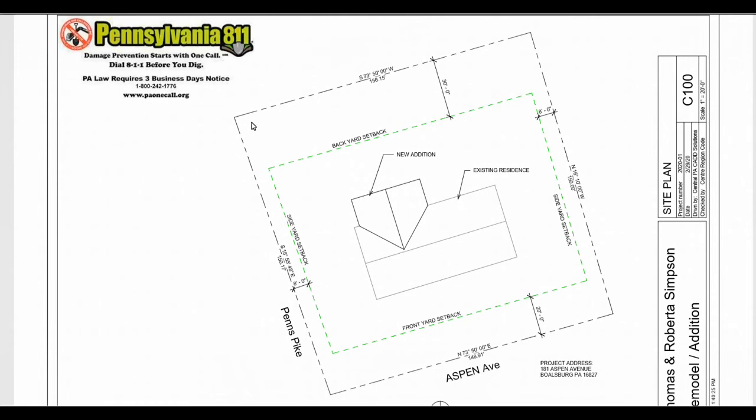And a lot of times in the corners, there would be iron pins that identify or locate the corners, and that would be your starting point. So a lot of times you may see those on the drawing. Like I said, a lot of older site plans, you're not going to see iron pins. If you would go out and actually look for those, you would find strange things for iron pins, whatever they happen to have laying around, like a signpost or something like that.